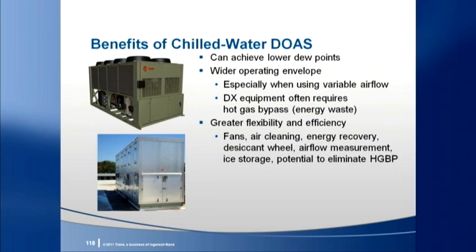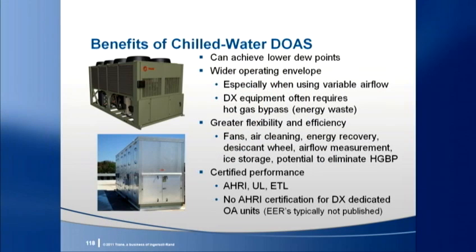Also with the chiller, you get AHRI certified performance, so you're sure to get what you paid for. There's currently no AHRI certification program for DX dedicated outdoor air units. Finally, using a chiller will typically result in a lower refrigerant charge than a DX unit. This can help achieve LEED EA credit 4.